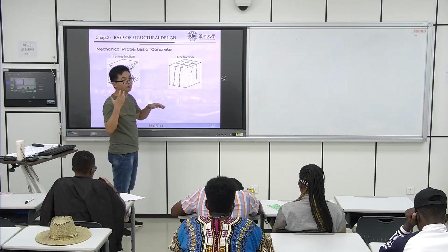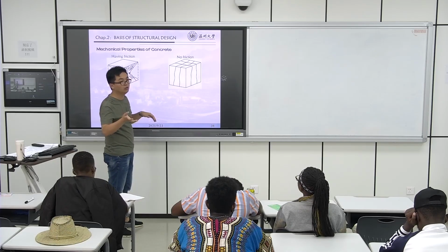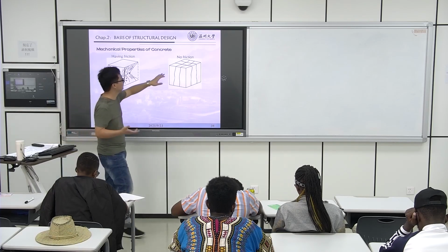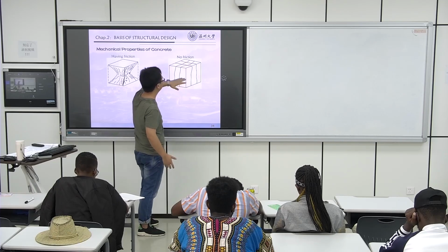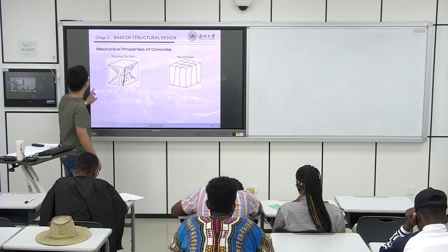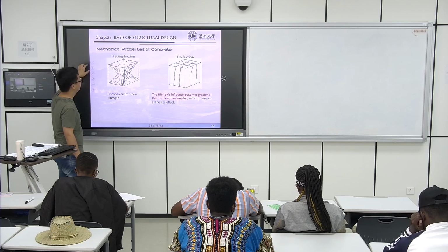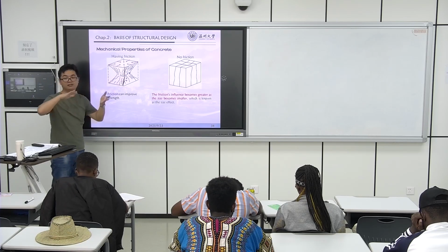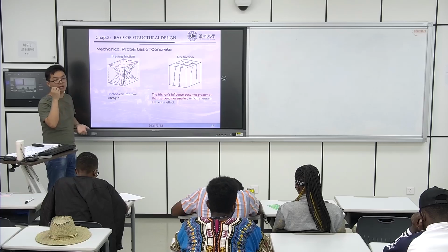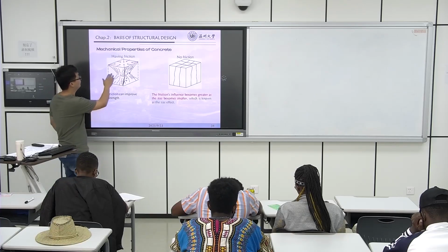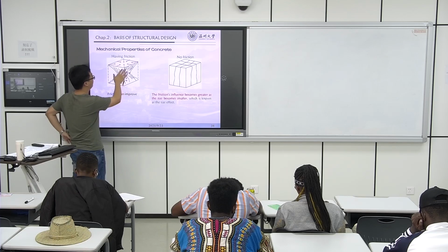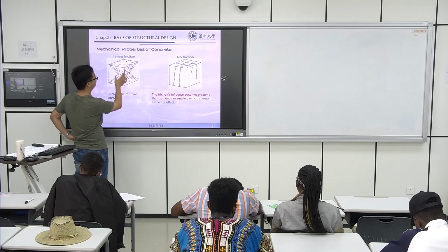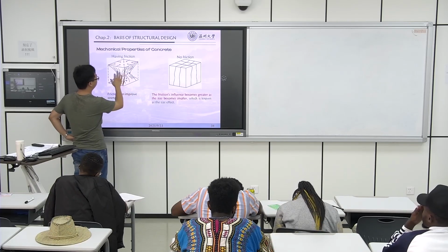And if we use some oil on the surface of the machine and the surface of the concrete cube, the failure mode will be different. Can you imagine, the surface touching the machine has friction, which will affect the specimen. And this surface, this part will be stronger than the middle part. So the crack.